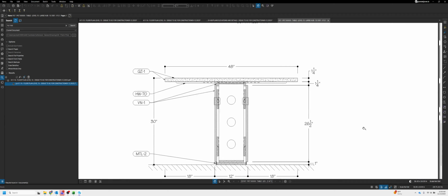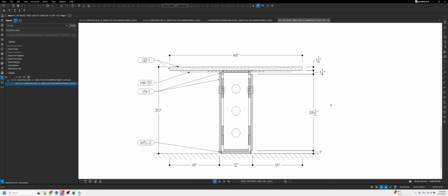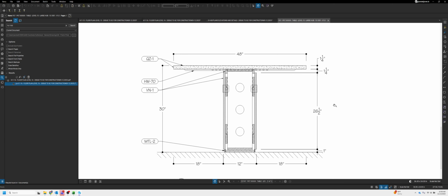One last thing before we get into CAD. Tables and islands, you can support these several different ways. When you have a countertop with a cantilever like this, where it overhangs, even if it's just one side, you want to start to think about how you're going to support that. One thing you can always do is there's a vast selection of different brackets that you can buy online to support countertops that overhang like this.